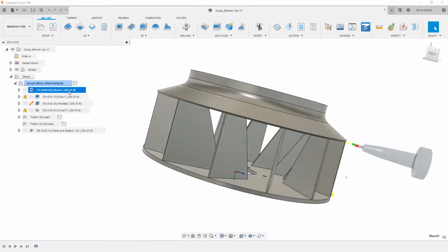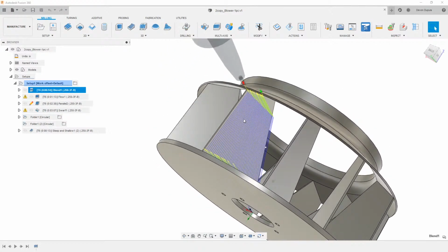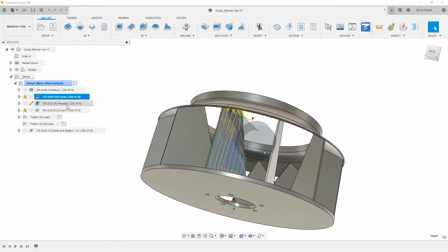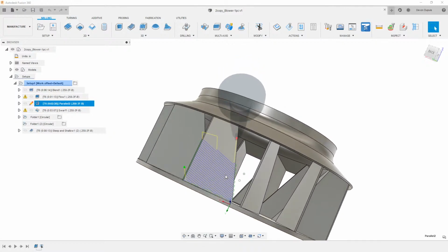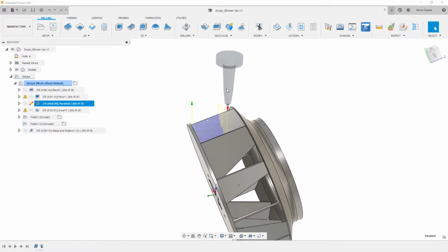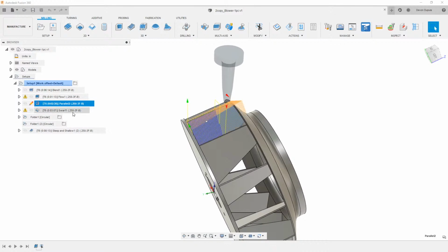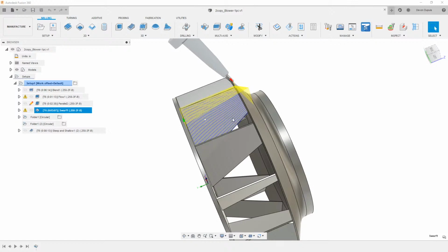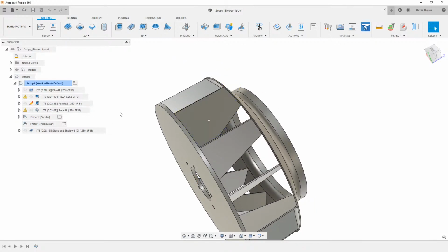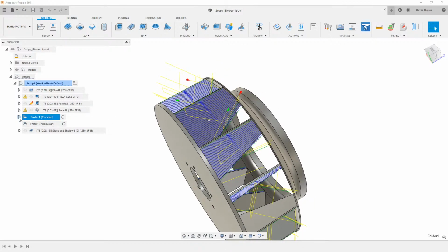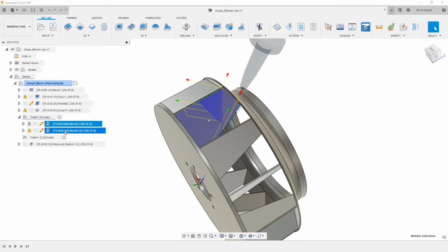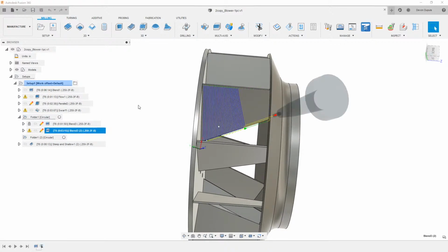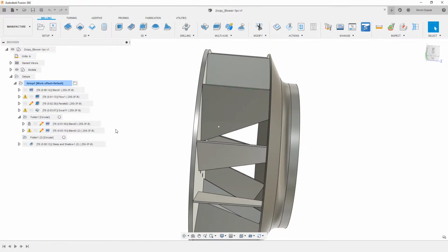So I was trying toolpaths like blend, which does okay, but it's hard to constrain this down. Flow, kind of a similar situation. A lot of noise in those toolpaths. Parallel is okay, but I had to manually come in here and make my tool orientations. Swarf was kind of the same thing. It just wasn't respecting the part because it's really only seeing the rails that I choose to drive my toolpath with. So in the end, for the customer, we decided on doing a combination of the two blends here and crossing it in the middle, and then patterning those around.